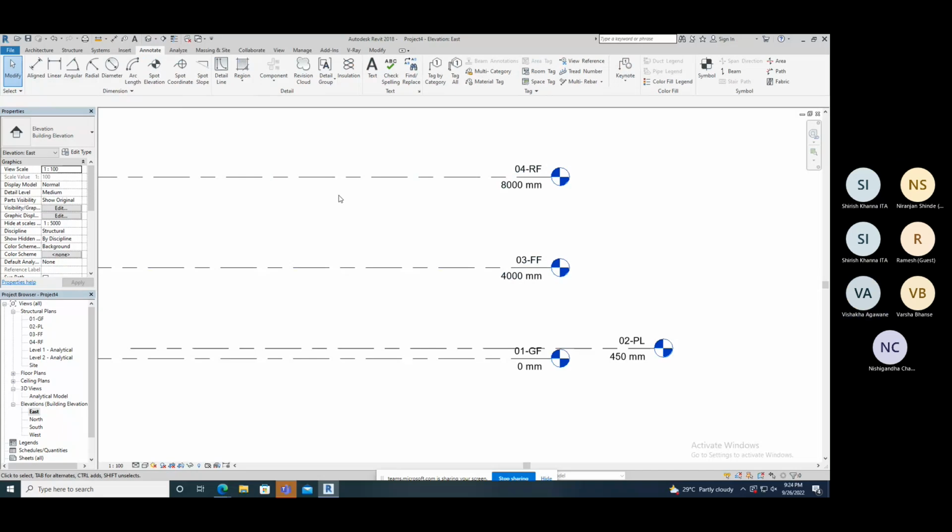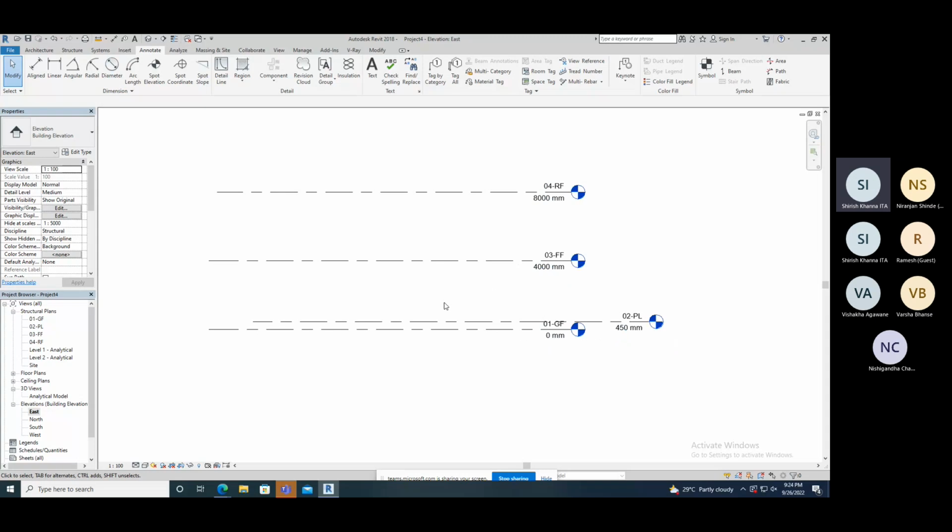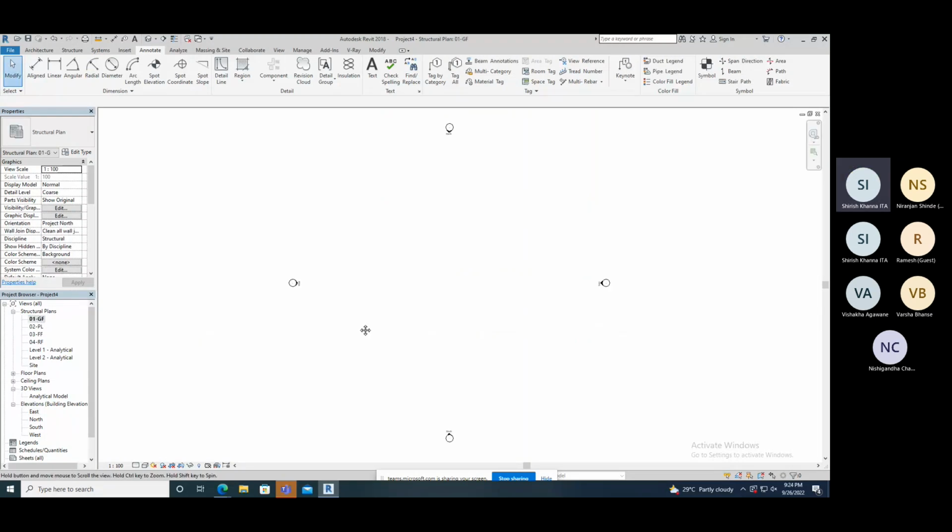Okay. Now, this is the levels portion. Now you are able to create the levels. The second thing is the grid, so that we can create one floor plan here. Suppose we are using the ground floor. Double click on the floor you want to work with. Ground floor, double click on it. Now you are in the ground floor.